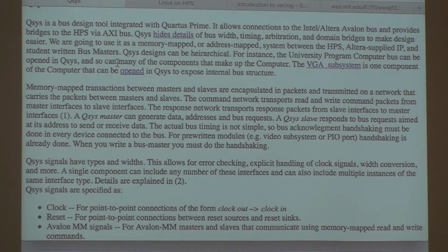And then when you got that going, you could delete that module and rewrite it if you wanted to. It's pretty easy. All it is is a parallel I/O port. The LED module is a generic PIO, which is draggable off of the menu. It's a generic PIO port that's been renamed LEDs and connected to the LED bus. But you could easily do that in Verilog.